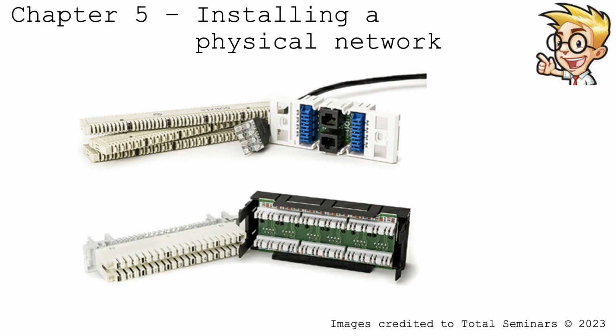Okay, so we were talking about punch downs before. So this is what a punch down looks like on a 110 punch down block. Some people call it a BIX block on the wall, this one. But different technologies. This one's called a Krone block. It's a 110 punch down block. So that's the back end to the patch panel.